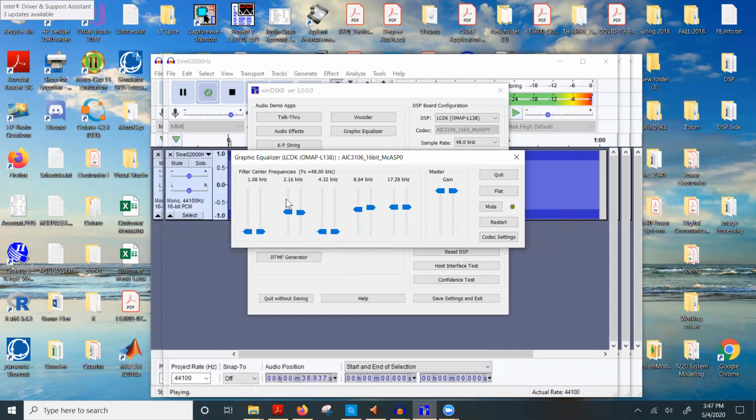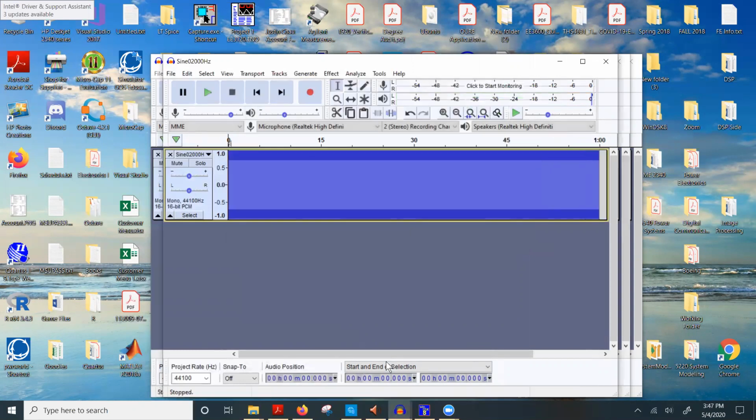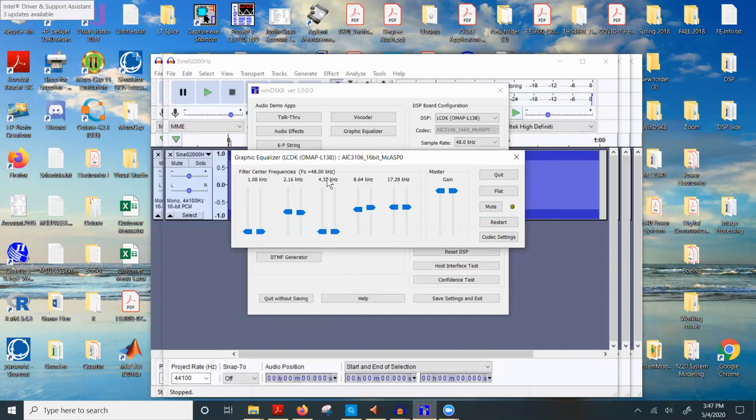Since the center frequency is around 2 kilohertz and the cutoff frequency of this first low-pass filter is 1 kilohertz, this band has a bandwidth of about 1K because it will extend down from 2 kilohertz to the end of the first filter at around 1 kilohertz, and will extend 1 kilohertz upward to 3 kilohertz over here. Then the next band above that, the 4 kilohertz band, will reach down to about 3 kilohertz here and 5 kilohertz on the other side. It's 1 kilohertz bandwidth as well.